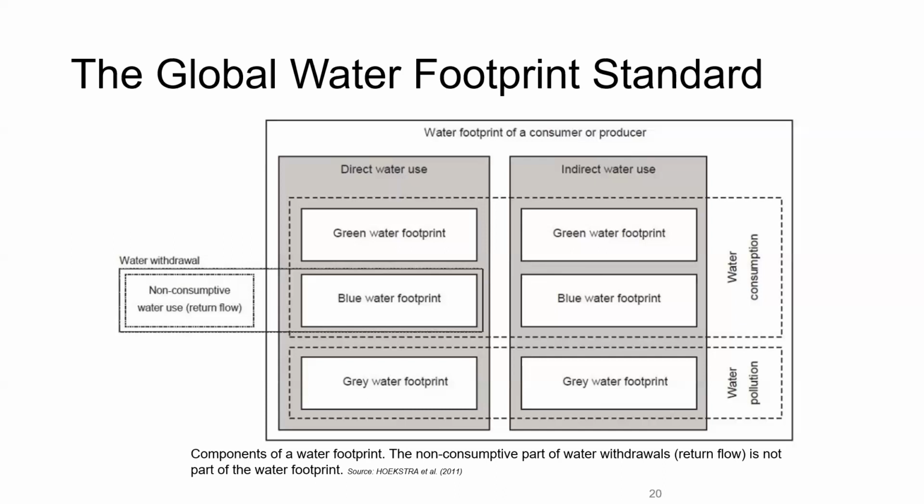How much water you are consuming, how much water you are sourcing from different sources, how much water you are recharging to the wells and ground, how much water you are storing at source and recycling and reusing within premises. And then this green and blue water can be converted into the gray water or polluted water. Suppose you have water like X plus Y. X is green, Y is blue. So gray water will be X plus Y. Why? Because total water you are converting into waste. But if you are recycling within the system, that means you are saving the blue water and gray water is being utilized in the system.